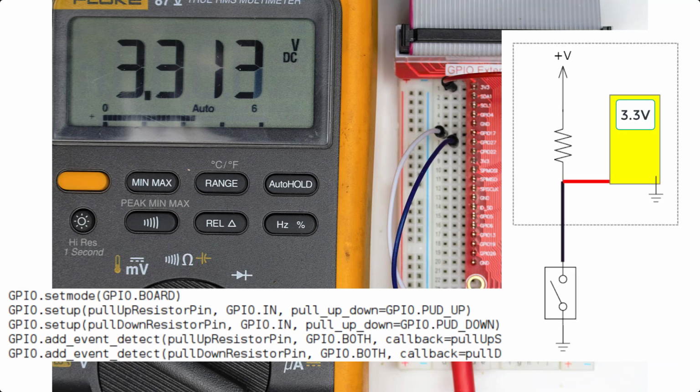Alright, here we have a pull-up resistor example to try to make sure that we're clear on what's happening here. So the dash box indicates that this is the inside of the Raspberry Pi. On a vehicle you would see something very similar that would show, like, the body control module, and it would have a dashed line that indicated that this is inside of the module. So this is inside of the Raspberry Pi.